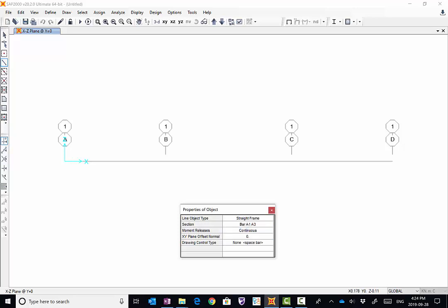So I'm going to start with element 1. If you click here on node 1, and then take it up to node 2 and click the left button again, this will give you element 1. Now you have to be careful. You have to change the cross-sectional area to A2, and then connect element 2 from node 2 to node 3, and then go back again, because element 3 has cross-sectional area A3, and connect from node 3 to node 4. And then we can close this.